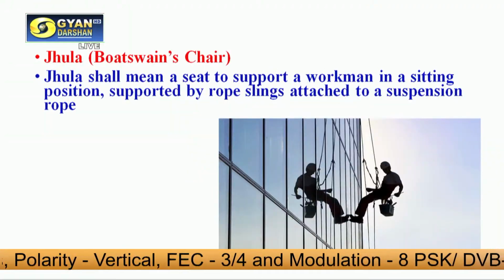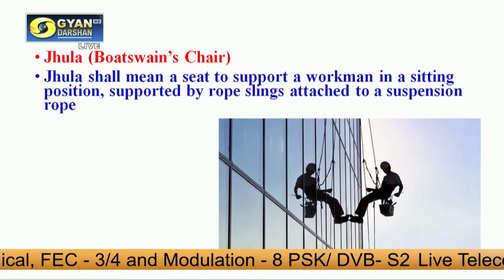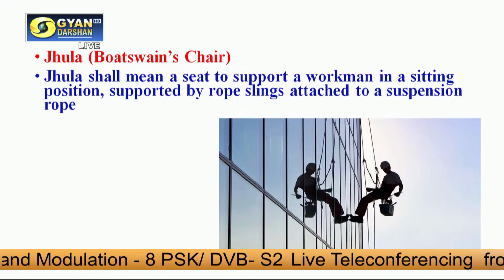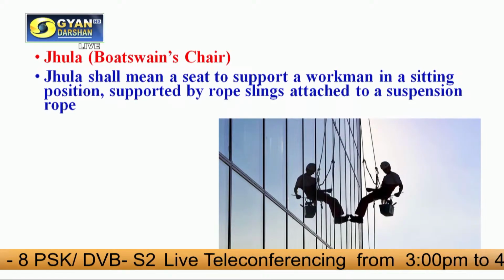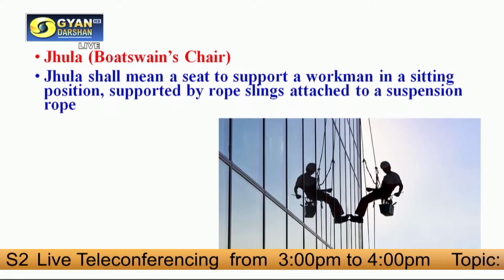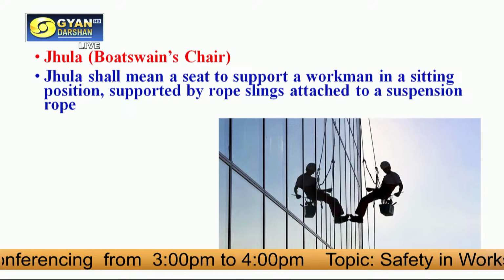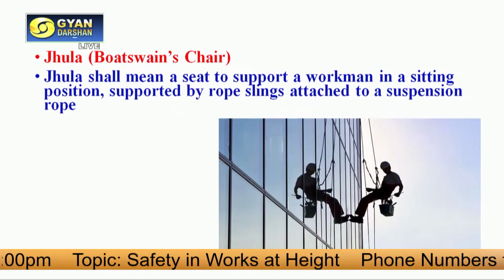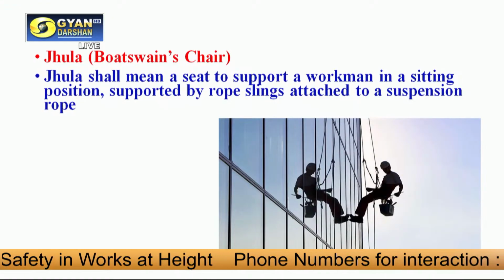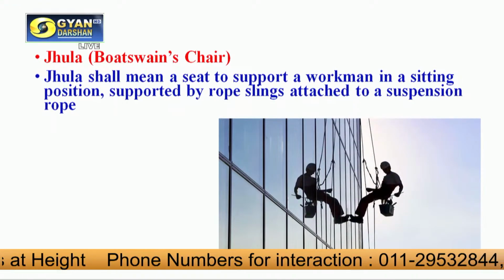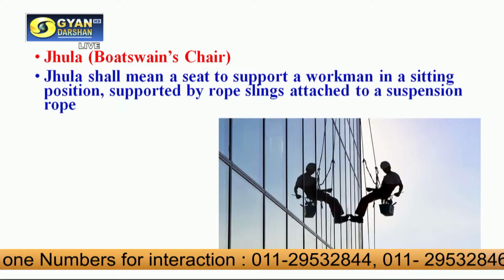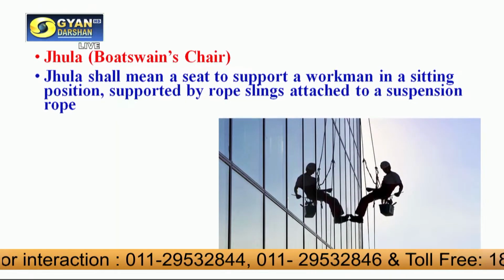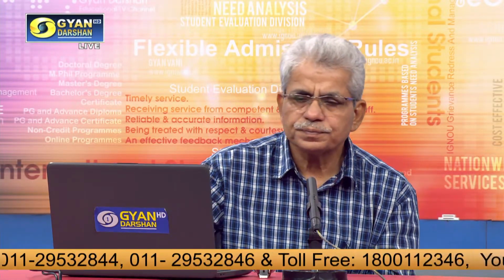Then jhula or bosun's chair. This is used in place of, you can say, the suspended scaffold, where only one worker is working and just cleaning the glasses or painting some walls, such type of work. This jhula or bosun's chair is used. This also comes under the scaffold category.